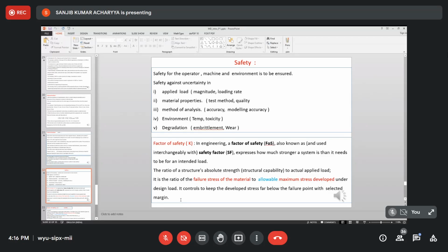That factor K is the factor of safety. Suppose we choose to use a factor of safety of 2. Then we have to divide 600 MPa by 2. We will get 300. Now we will say the allowable stress for this material in this case of design is 300 MPa, and the designer has to use 300 MPa as the allowable stress, and accordingly he has to design.